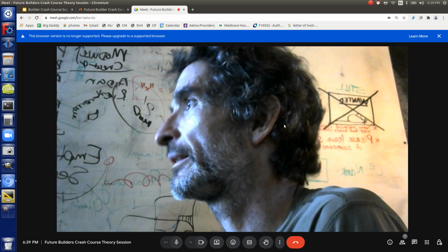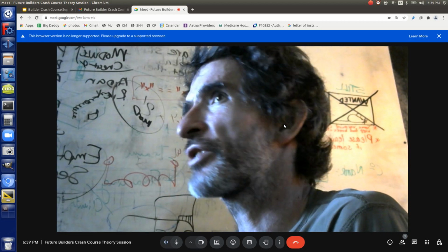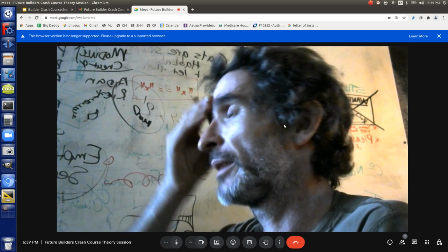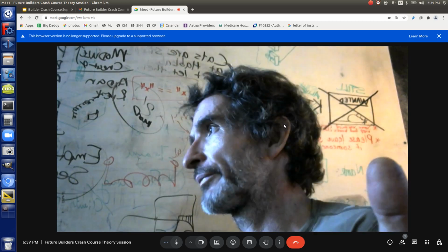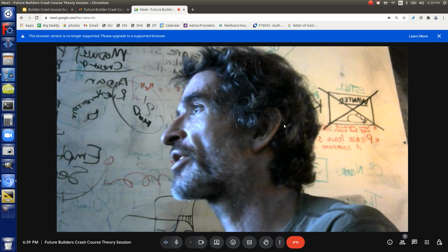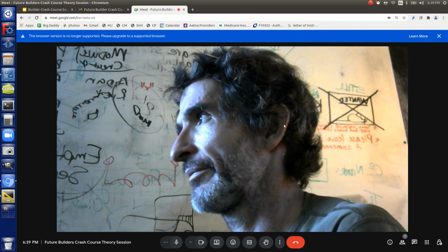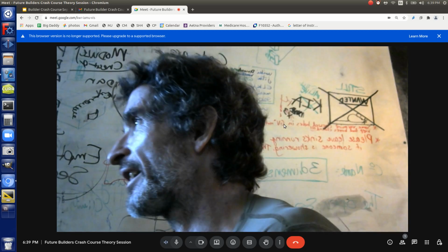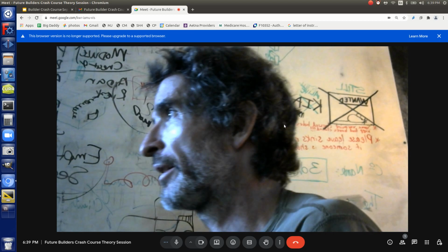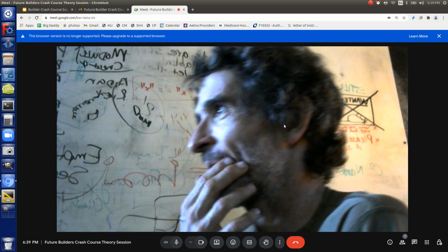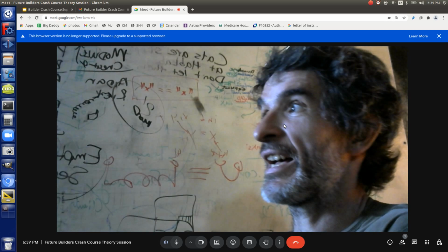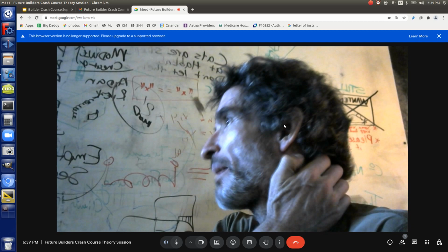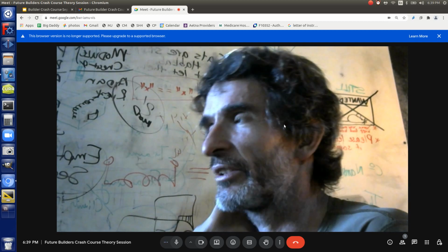So in other words, if you got a wall that's 1 foot thick, because that's how we built them, and you got 4 feet, that's 8 times that. That wall section itself can hold 16,000 pounds, assuming that the actual load is way below that, so you're not getting into these other crumpling or edge effects. So get a load of that. What can you put on a brick house like that if you actually made the walls proper? You can drive on top of that. There's no problem. It can hold a lot of weight.